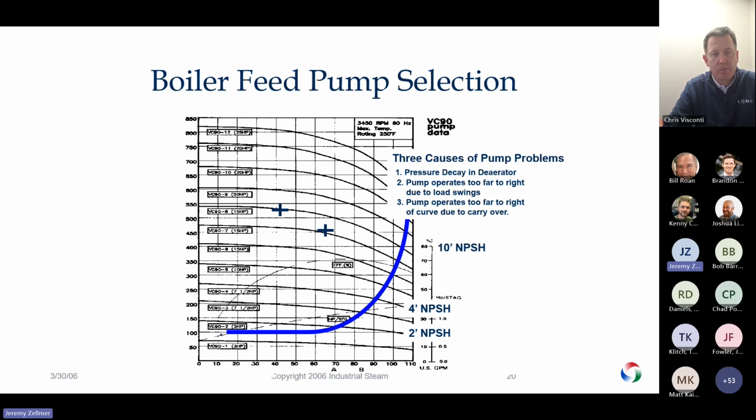And then we want to make sure we can still back up, but we don't want the pump wanting to keep going out on this curve, where we're flowing a lot more but don't have the stand height, and we start developing NPSH issues.